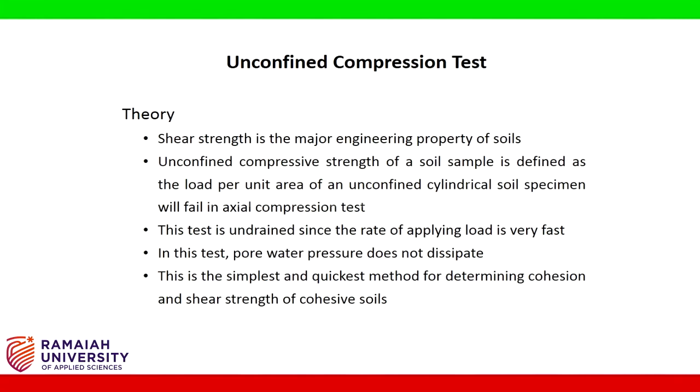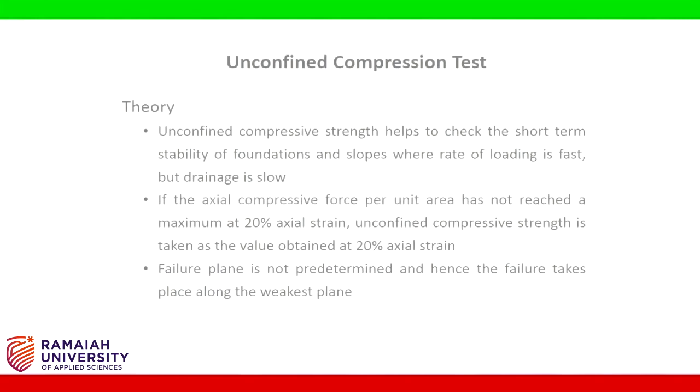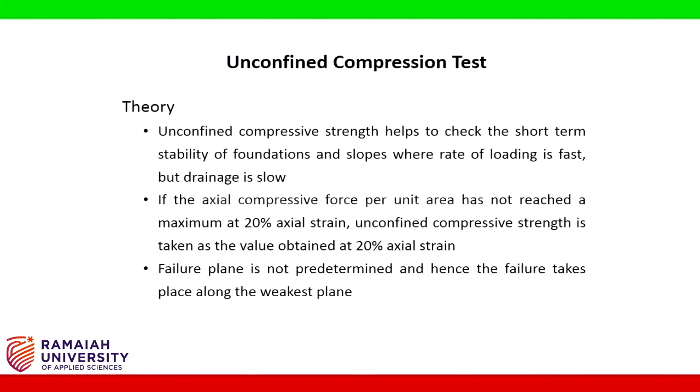This test is undrained since the rate of applying load is very fast. In this test, pore water pressure does not dissipate. This is the simplest and quickest method for determining cohesion and shear strength of cohesive soils. Unconfined compressive strength helps to check the short-term stability of foundations and slopes where rate of loading is fast but